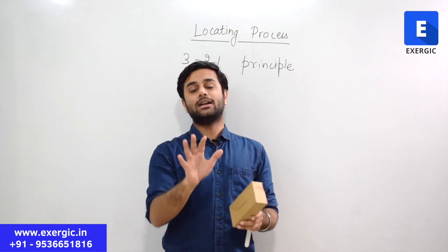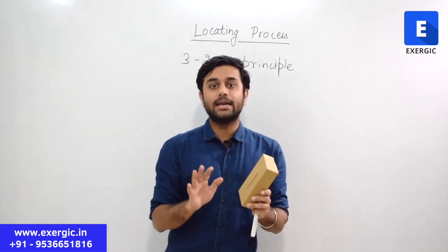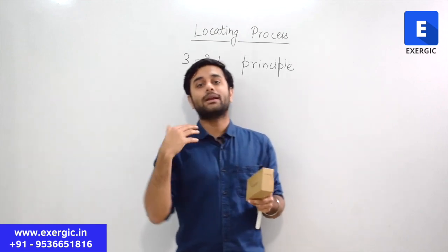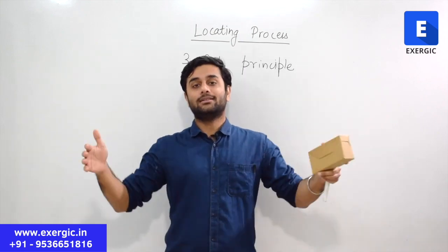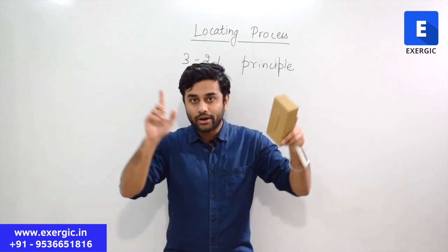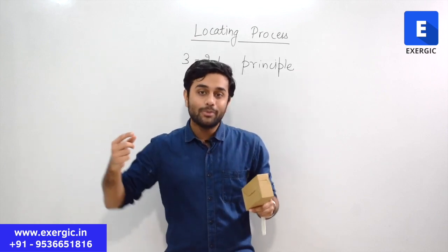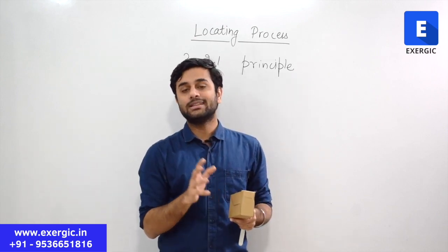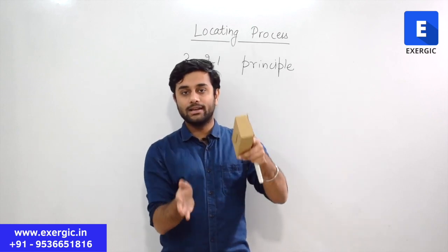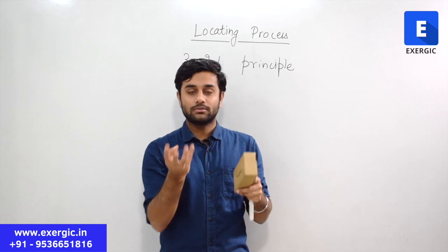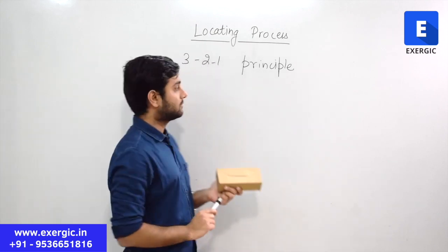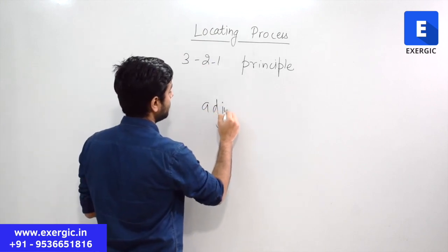And third, a practical tip. There are certain shapes, because the workpiece is not going to be of this simple shape. The workpiece can be complex in shape. It can be large in dimension, more in weight. I have already told you that if weight is more, you may have to provide additional pins. Then what to do? 3 pins you can support without any wobbling. If you add 1 more, wobble will start. What to do? The 4th pin will be adjustable.